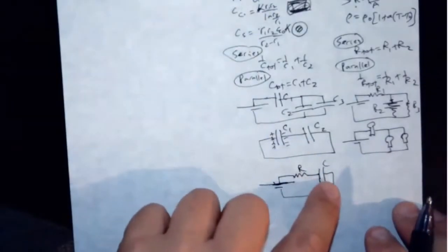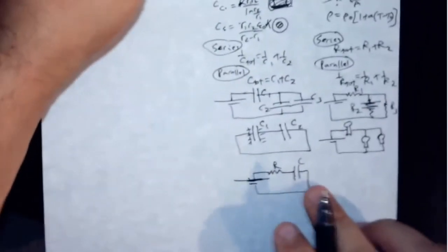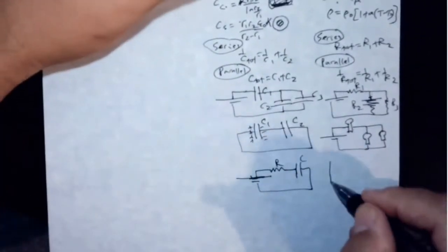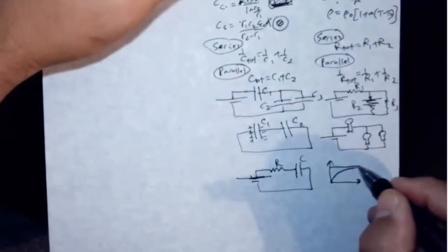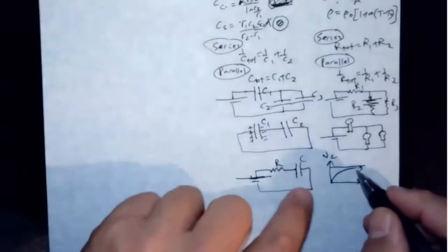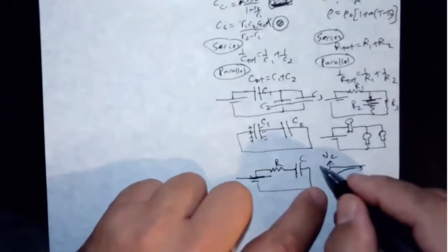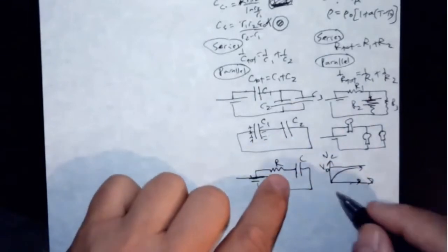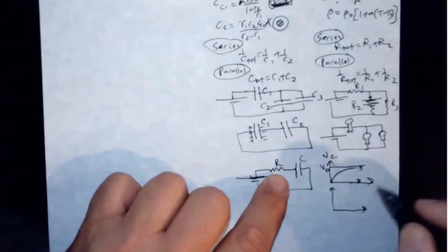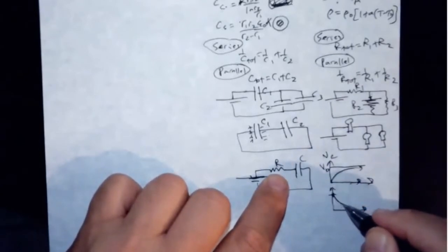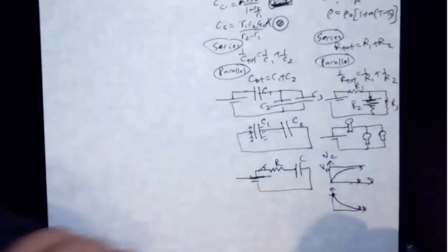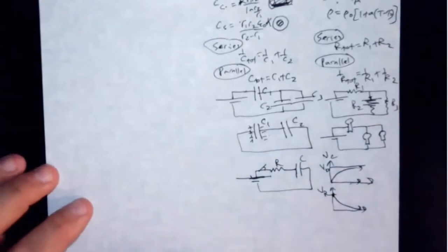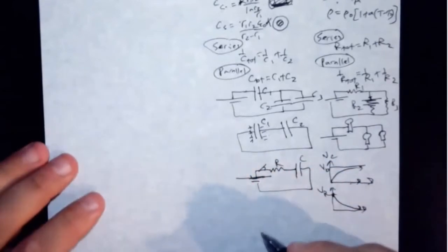What kind of behavior does the voltage of the capacitor behave? We saw that the voltage of the capacitor charges asymptotically until it reaches its final charging state, right? It reaches the voltage of the battery. And then the voltage of the resistor goes down all the way to 0. This is if it's a charging RC circuit. All right, so voltage of resistor. But then you can have variety of those kind of problems too.